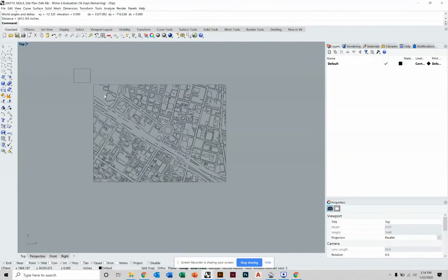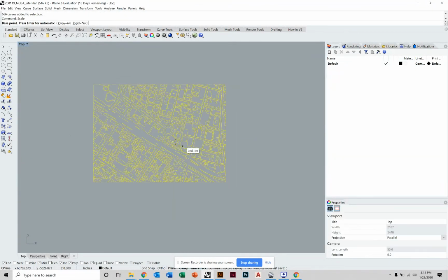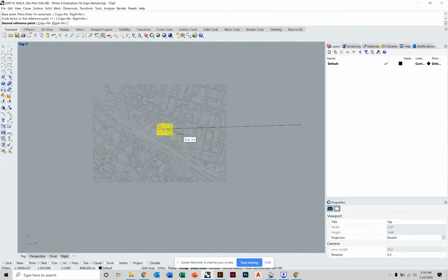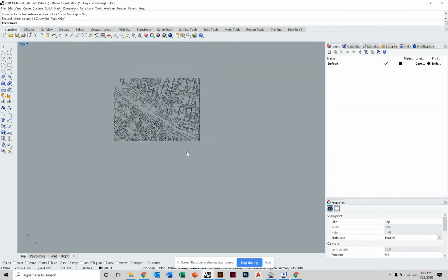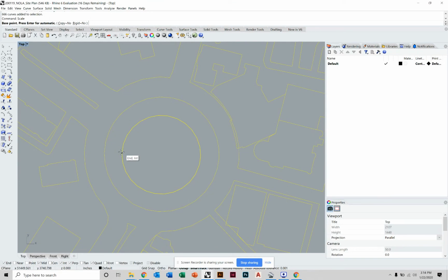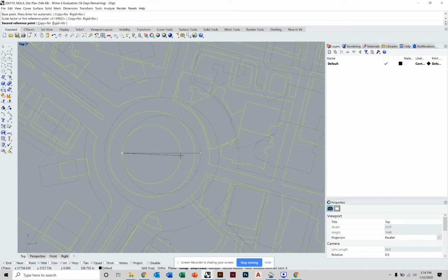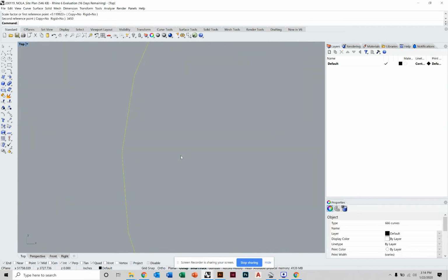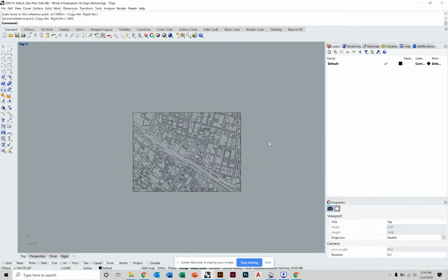So that's what I did. If I mess up the scale just for kicks, if it's much smaller, what I would do is select the whole thing, type in scale. What did I say? 3,450? Say 3,450, enter, and it's back to scale. It's just like that. Reference to streets, depending on the number of lanes, is also a good reference. Yeah, you can use buildings.